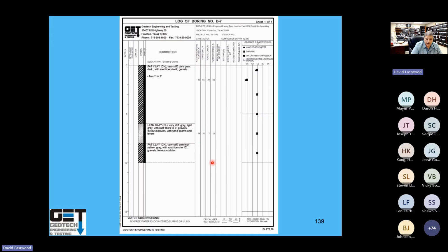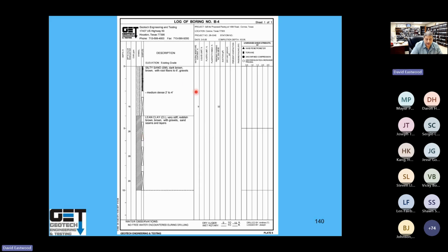So when we do a roadway job, we do borings for a depth of 10 feet. You got fat clay here, got a PI of 38. Soil strengths here are pretty good, 1,000 PSF. You can carry the paving load. And of course here, we didn't hit any water. There was no water. Here's the other side, sandy, silty soils, and 32% passes number 200 sieve. So that, you got to be lime fly ash stabilized. It's going to pump. We've got a perched water table here.